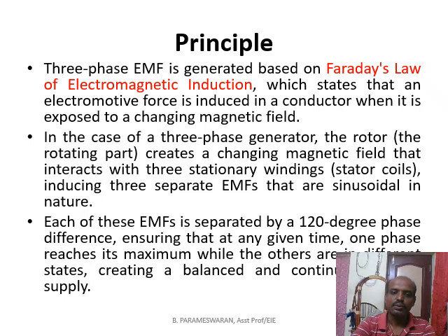Next, what is the principle behind this EMF generation? The principle behind this is Faraday's law of electromagnetic induction. It states that an electromotive force will be induced in a conductor when it is exposed to a changing magnetic field. So what does it mean? When a magnetic field is there, if you place a conductor in this magnetic field, there is a cutting motion occurring.